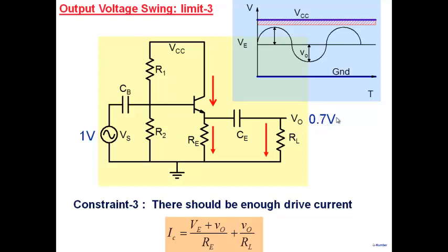What happens then momentarily? Note what the net base emitter voltage is. The net base emitter voltage that you see here is equal to DC plus a small signal AC. Remember, every voltage has a DC part and a sinusoidal part. So VB will be equal to 0.7 plus small signal VB. I've applied 1 here, and we are saying this is 0.7, so this value becomes 0.3. And now note, how does current increase with base emitter voltage? Exponentially.